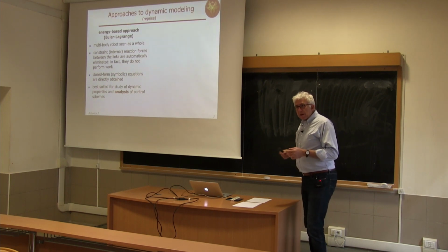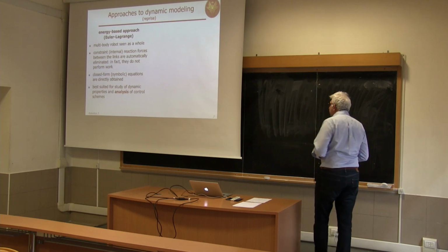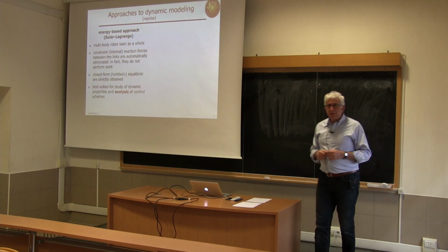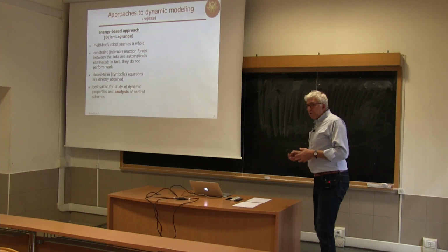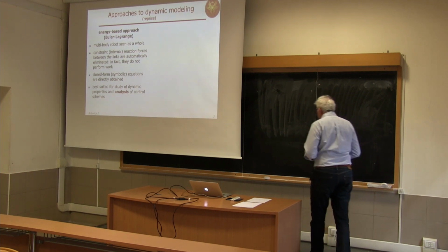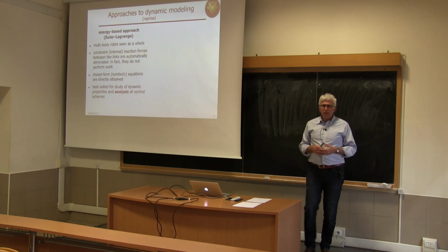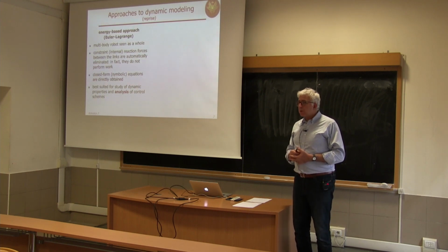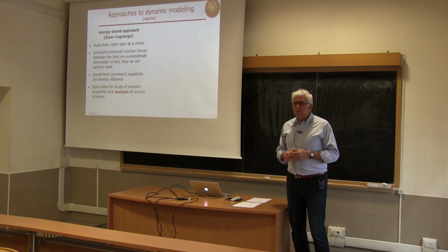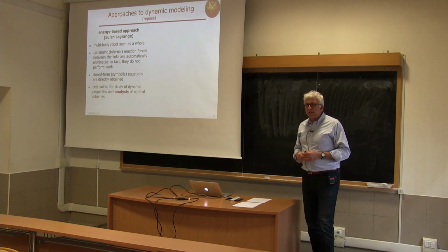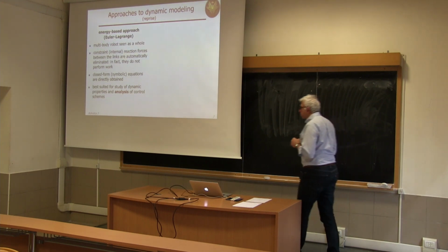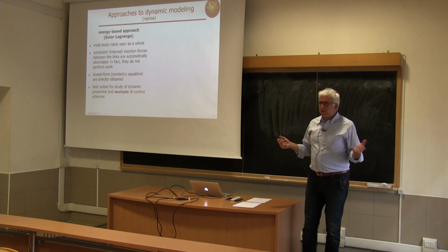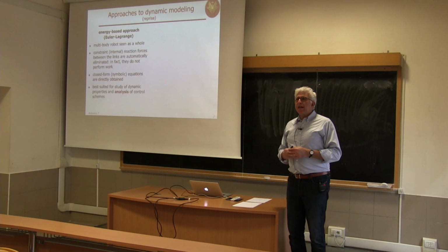And this is the reason why we can safely perform simulation of our model, so solving the direct dynamics, because we need to invert there the inertia matrix, and this is never singular. Moreover, we have investigated some internal structural properties. For instance, the fact that if you factorize properly the quadratic terms of the Coriolis and centrifugal forces, quadratic in the velocities, with a suitable matrix S, which can be computed from the Christoffel symbols, then this fancy property holds: M dot, so the derivative of the inertia matrix, minus 2S, is a skew-symmetric matrix. We will use this later in control design.